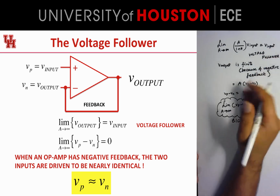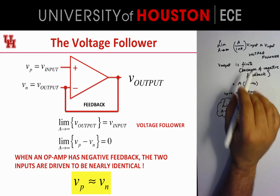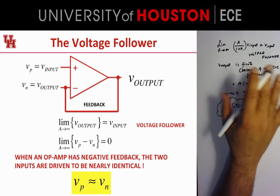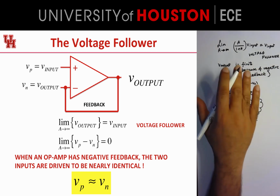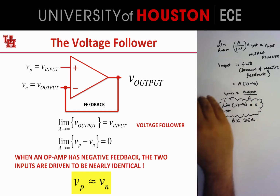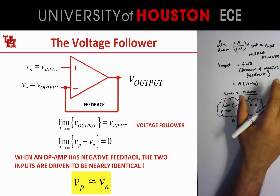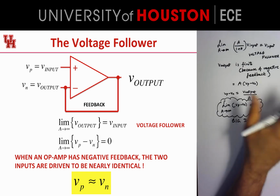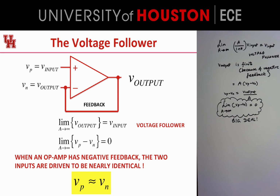You might ask, what's the point of simply following a voltage? What it's doing is providing a strengthening of the signal. Suppose the input voltage is coming from a very weak source. Without perturbing that weak source, it'll provide you with an equal voltage at the other end that can drive a much heavier load. So an amplifier is a signal strengthening kind of device.